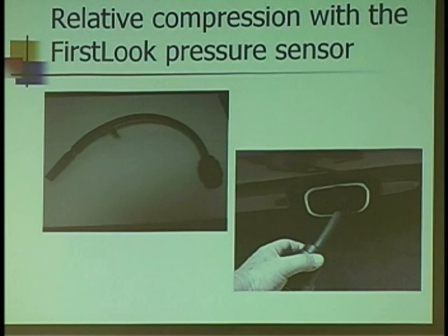How many of you guys are IATN members? Okay. Go to the tools and equipment forum. Some guys are making their own. They're getting a $5 piezoelectric sensor down at Radio Shack, and they're buying a little baby bottle and an old tire valve stem, and they're making their own pressure sensor.